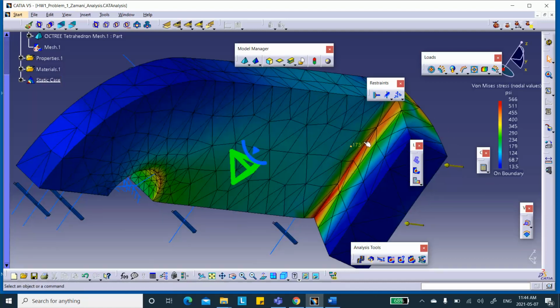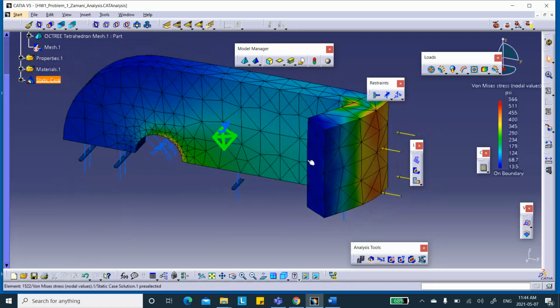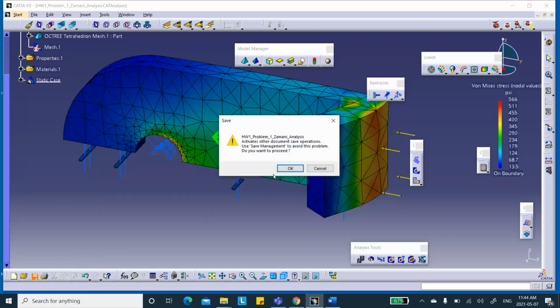This may be good-looking garbage, but you really should put fillets there. The fillet reduces the stresses, and the mesh must be fine enough, etc. None of those we're looking at here. Okay, so save it, save everything.